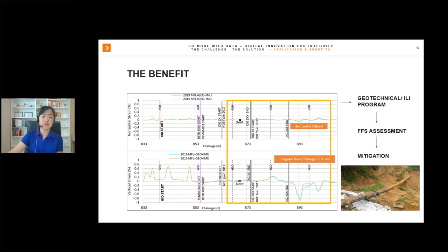The assessment of data, as shown in the bottom half of the plot, indicates the strain is most likely attributed to the result of the 2017 dig excavation and the subsequent reburial and settlement of the pipe. We can use these plots to identify efficiently and accurately whether pipeline strain is construction-related or an area of land movement event with the potential of more severe consequences in the future.